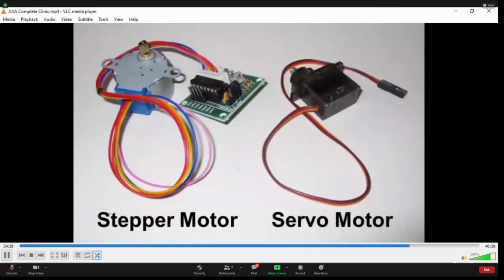This is the first project where I used motors. Arduinos can drive small stepper and servo motors directly without a separate motor shield. I used servos because they are absolute in positioning. They always know where 0 degrees is. Steppers are relative. I wanted the tree and the lumberjack to always know their starting position.